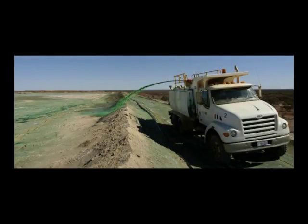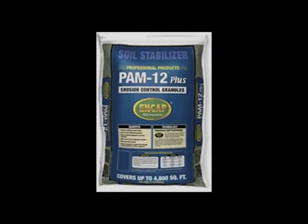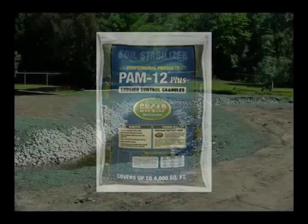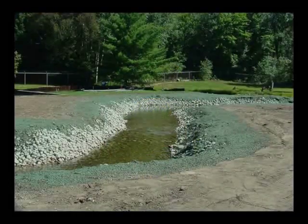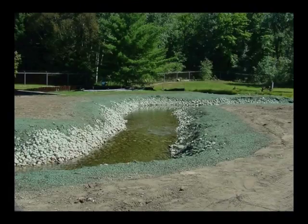The chemicals penetrate into the soil and bond the individual soil particles, making them resistant to the forces of wind and water. One class of chemicals that are commonly used are polyacrylamides, or PAMs. Be aware that the surface application of certain chemicals may be regulated or even prohibited, depending on location and proximity to surface waters of the state.